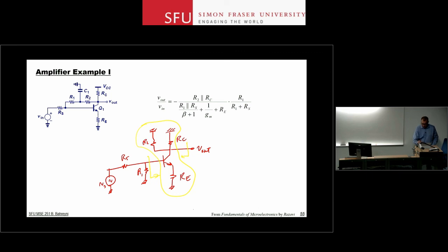And then, you know, what is the voltage that appears here? Well, it's the input resistance that you have, R in and R out, let's call it. You can find them from the formulas and then put that input resistance in parallel with R1 and look at the voltage divider between that combination and RS to figure out what is VI and so on and so forth, right?